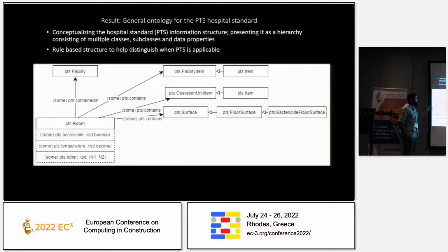That's where this comes in, but it also helps us with the distance that we need to know about certain rooms. It's not always necessary, but if anything, you have very specific rooms next to each other. For example, a banal example is that in the regular toilets in an ICU unit, there should be a specific distance, and adjacent to these ICU units you should have specific rooms. You don't have common areas right next to, for example, a surgical room, and so that sort of mindset.